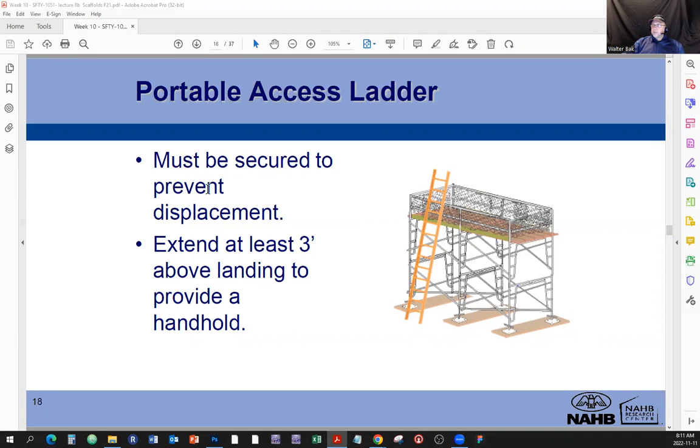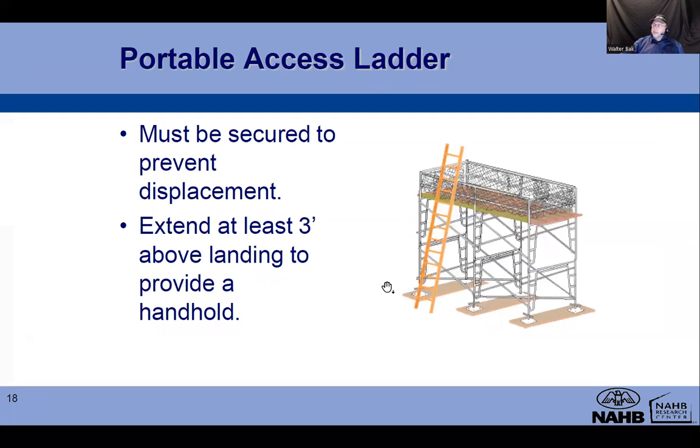Right? Ladders must be secure to prevent displacement. Secure from the top, secure from the bottom. Extend at least 3 feet above the landing surface to provide a handhold. So that's the same as the rules that we studied with the ladder. Whenever you have the landing surface, so here is your starting point at the bottom.